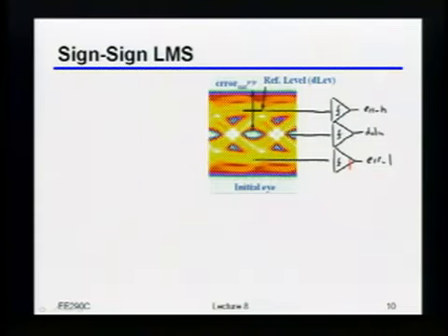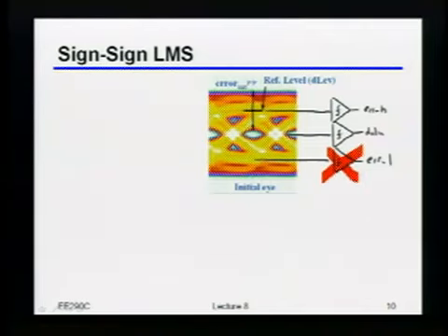We also said that if we really wanted to be lazy, and remember, a lot of this is about being lazy because the channel doesn't change all that fast, we really don't want to be paying a lot of extra hardware and power for things that are just slow tracking things. So we said you could even get rid of one of those error samplers, because as long as things are reasonably linear, the errors you see on the upper level should be the same errors you're seeing on the bottom level. As long as you're willing to throw away half of the possible updates, there's no reason you need both of those things.